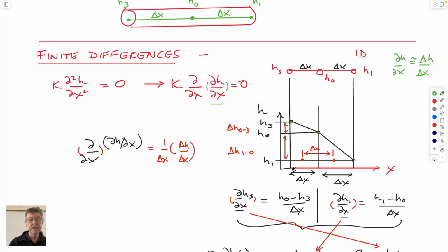So if you look at dividing your aquifer into the x direction and head, and you look at plotting the value of that head at maybe 3 locations as you go downstream, then what you can do is calculate what the value of dH dx is, which is delta h delta x, which merely says that you linearize these.